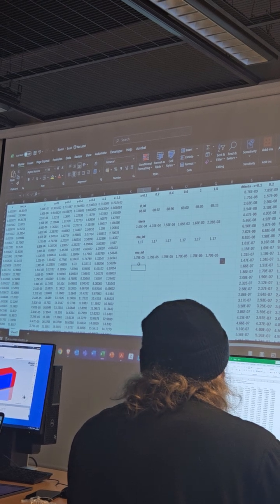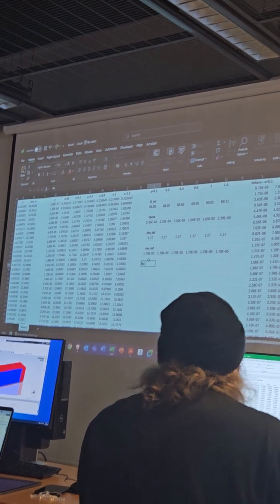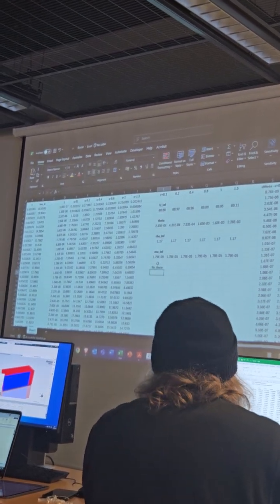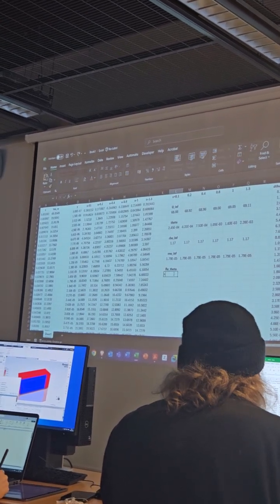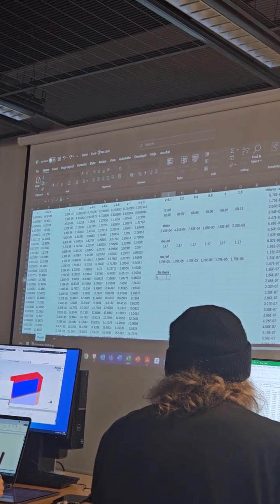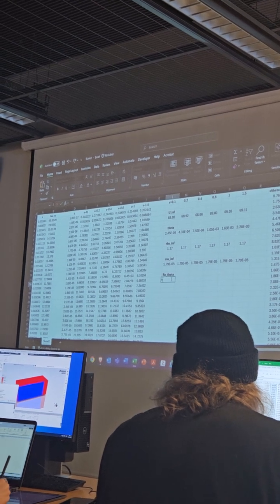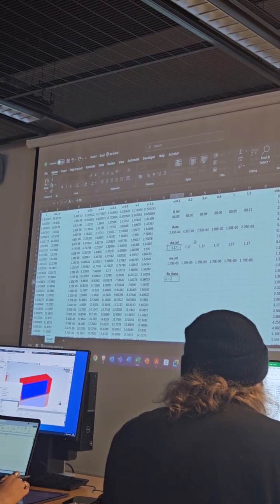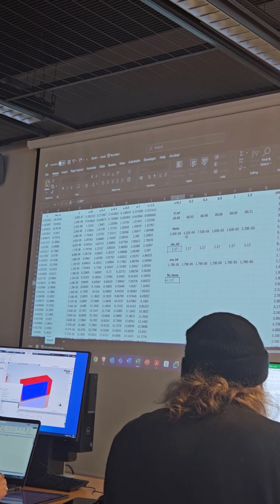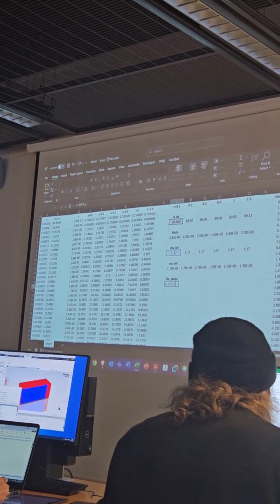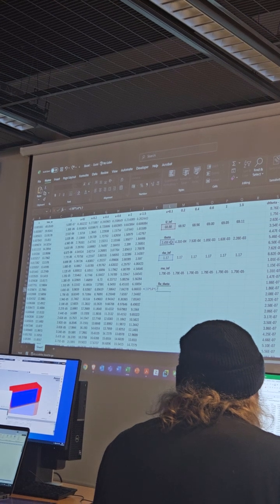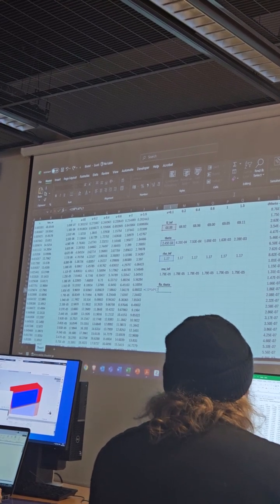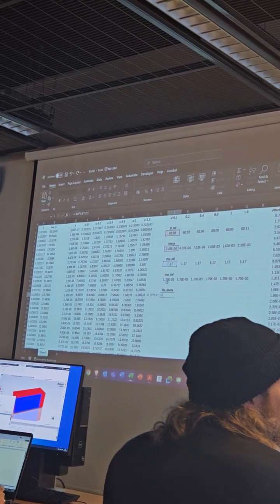Now that we have these values, we can calculate the Reynolds theta at each x value. So this is going to be equal to, following the formula there on the whiteboard, rho infinite times u infinite times theta over mu infinite.